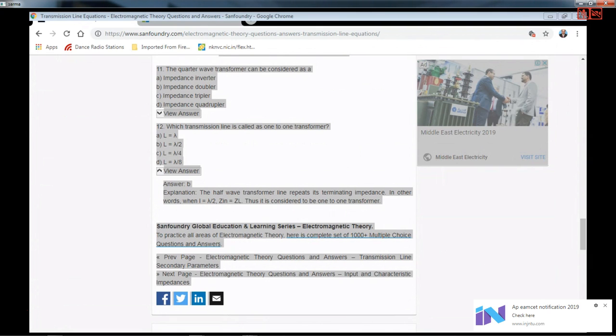So 2 beta z prime minus theta gamma must be equal to the voltage minimum location phase, which is e power minus j pi. So e power minus j pi is -1. Thereby theta gamma, that is the reflection coefficient phase value at the load, can be estimated by knowing the distance to the first minimum from the load and finding out the beta value from the given signal parameters, like the frequency of the signal.